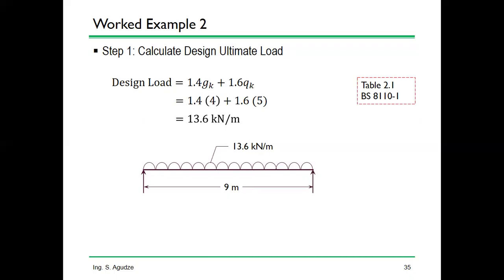So if you know the formula for calculating maximum moment, apply the formula, draw the bending moment diagram, and off you go. If you don't remember the formula, or if there is no such formula available in books, then you have to calculate the reactions, cut sections, and calculate your various bending moment values. And after that, you draw the diagram.